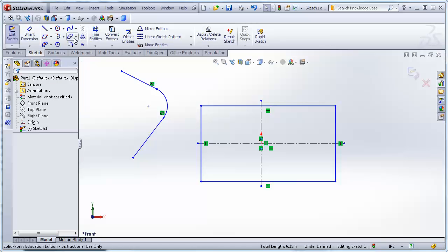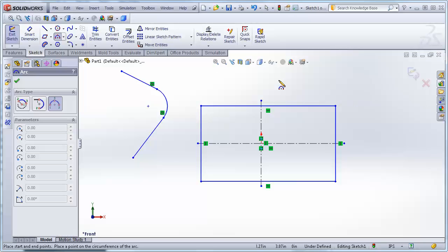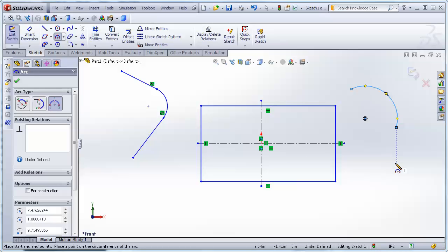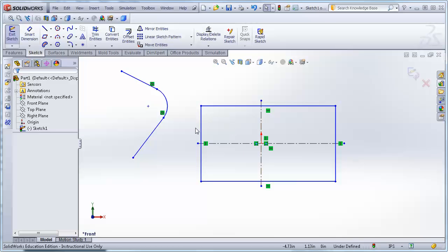So I'll pop up these constraints every now and then as things go by. So I'm going to leave that one alone. What else do we have for arcs? We have a 3-point arc. And I'm going to simply go click, and we'll locate another point on the arc. And then the third point is the location of the center. And I'll click, and that's the 3-point arc. And I will Control Z out of that one. I'll leave that one hanging around. Although if I leave too much stuff on the screen, I get more snaps than I'm really interested in.